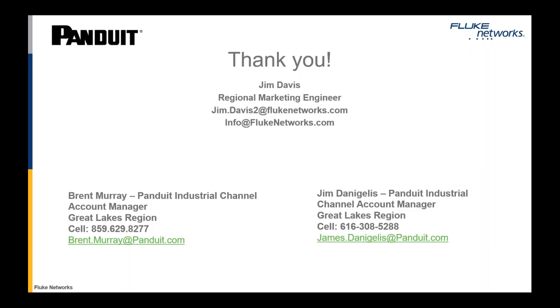And then there's another standard. Mike mentioned it. I should have brought it up more. The TIA 1152 standard, now in the A revision. That talks about what tests we're going to run in the field and how we're going to run them, and the accuracy. Within the 1152 standard, the values for TCL are specified, but it is not a requirement of the field testing. So yes, the standard specifies what the values are for TCL, but it's not mandatory to run the TCL tests.